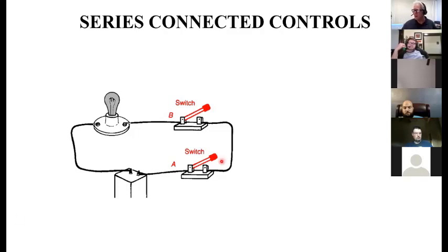So what I do over here, instead of having this as a light bulb, I say this is your motor that goes to your conveyor belt. And these little switches are going to be under the seats, just like the seat belt switch under the seat on your riding lawnmower. And by gosh, if only one of them sits down, it won't work. Both of them have got to sit down before that conveyor can run. They've got to both be in their seats for that conveyor to run. If either one of them gets up, it's going to stop.